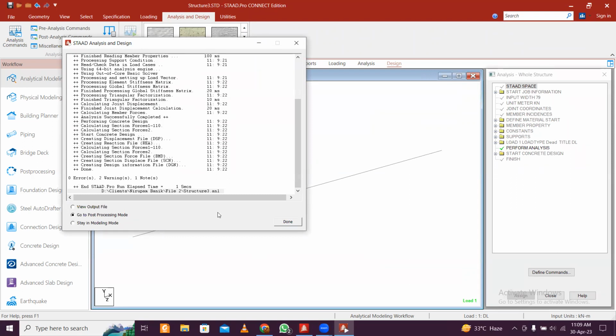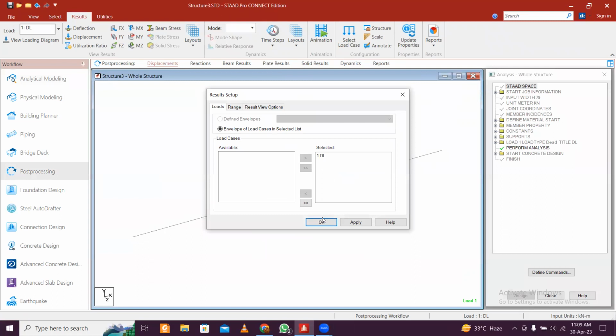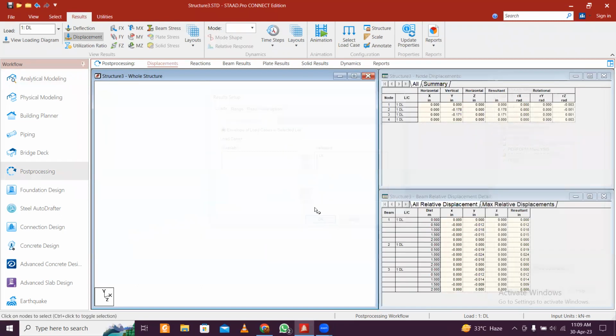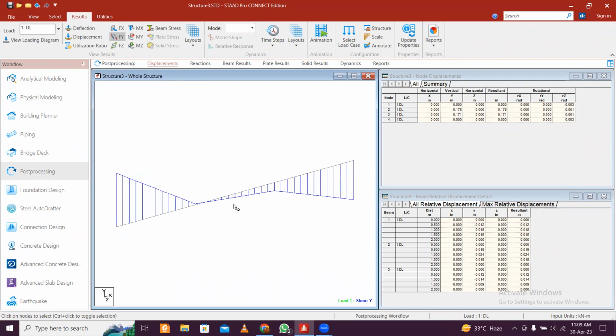You can just click on this go to first person, go directly to go. Otherwise, you can do like I did previously by pressing this one. Obviously, just click on apply and OK, and press Control. Press Control and plus to see the deflection of this beam, and similarly, just let's see the bending. Shear force diagram. Shift and plus. Control and plus to see the bending moment. Shear force diagram and the moment here.